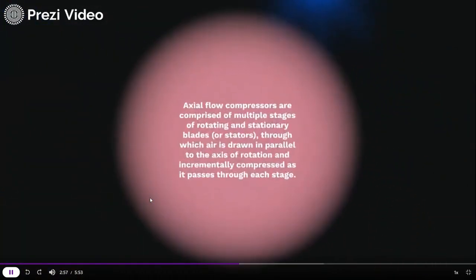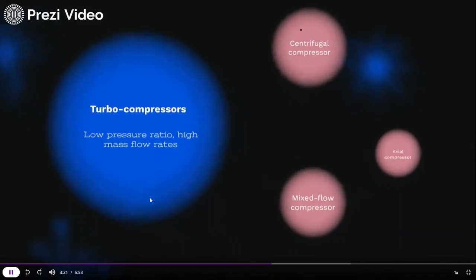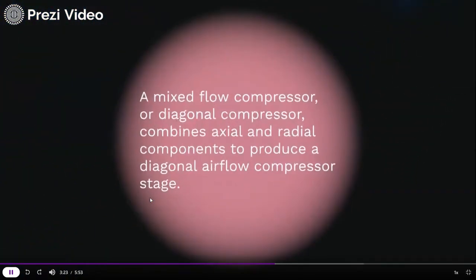Okay, the next one is the axial flow compressor, comprised of multiple stages of rotating and stationary blades, or rotor and stator, through which air is drawn in parallel to the axis of rotation and incrementally compressed as it passes through each stage. Okay, the next one is the mixed flow compressor, also known as the diagonal compressor. A mixed flow compressor combines axial and radial components to produce a diagonal airflow compressor stage.